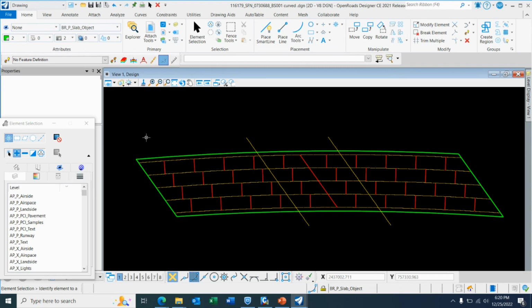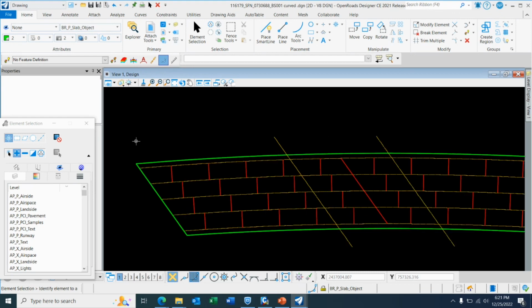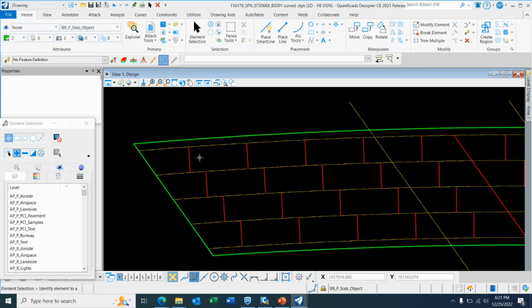Now for finite element analysis, we will divide our beam into a number of elements. To determine the number of elements, you should consider two factors. First, how accurate results do you want? And the second, the analysis time will go up with element numbers. In our case, I will just divide beam elements based on the intersection between other structural components rather than dividing into a random number of elements. But you can divide it in as many parts as you want, but you should be careful about the analysis time and the amount of effort that goes with increasing number of elements.